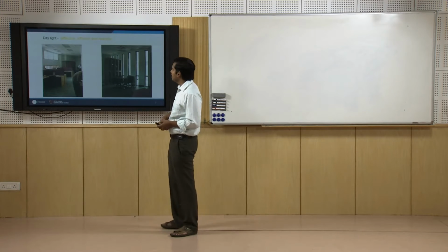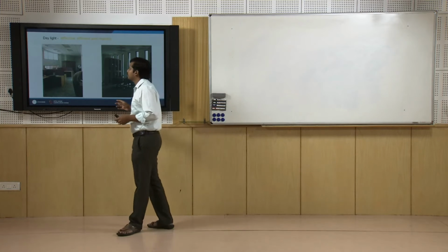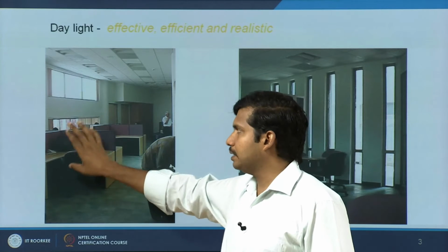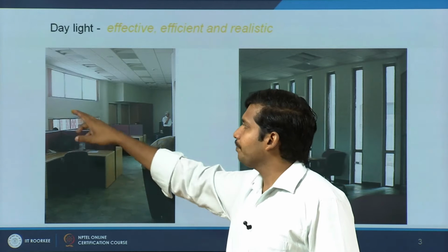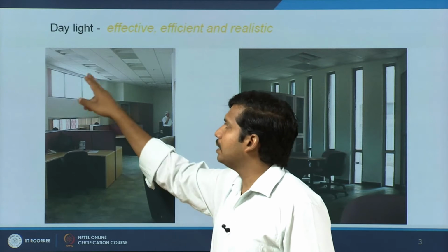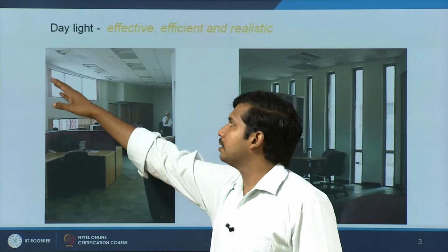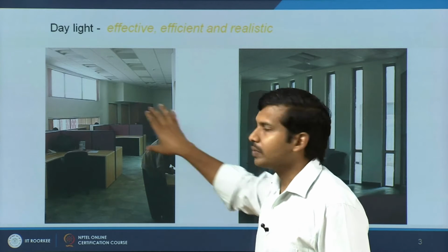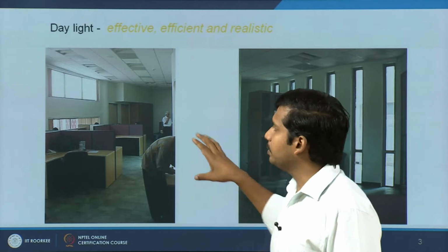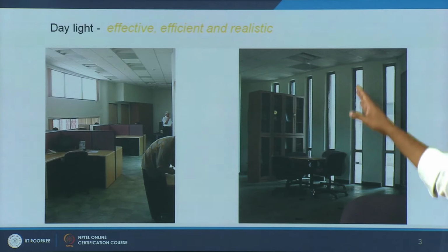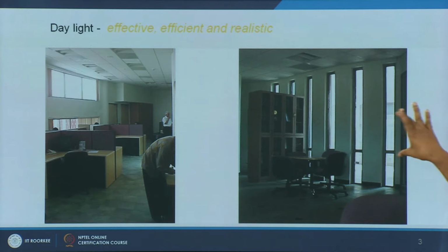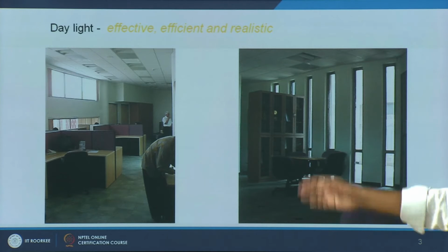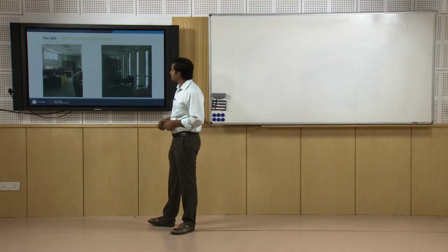light into the building. Instead of having single large panel windows, for example, you can have two clear sets of windows glazing, one catering to the work area close to the periphery, the other the typical skylight or the top part of the thing can be split, which will throw light onto the interiors of the building or the core areas of the building. The other simple option is, instead of having linear horizontal elements, you can have vertical, where you have a better throw of light far to the core areas of the building.